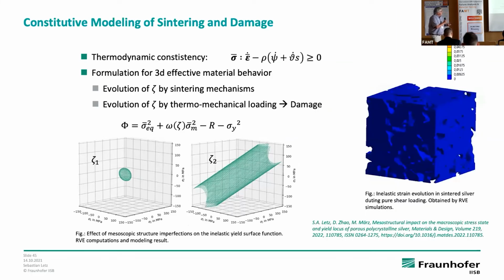And with this set of information, you can now say, okay, this is a Von Mises plot. These are the strains in the different space directions. You can say, okay, this is acting inside. You have elastic behavior inside this three-dimensional space, so everything is okay. But outside, you would have a plastic deformation, which may lead to a failure.